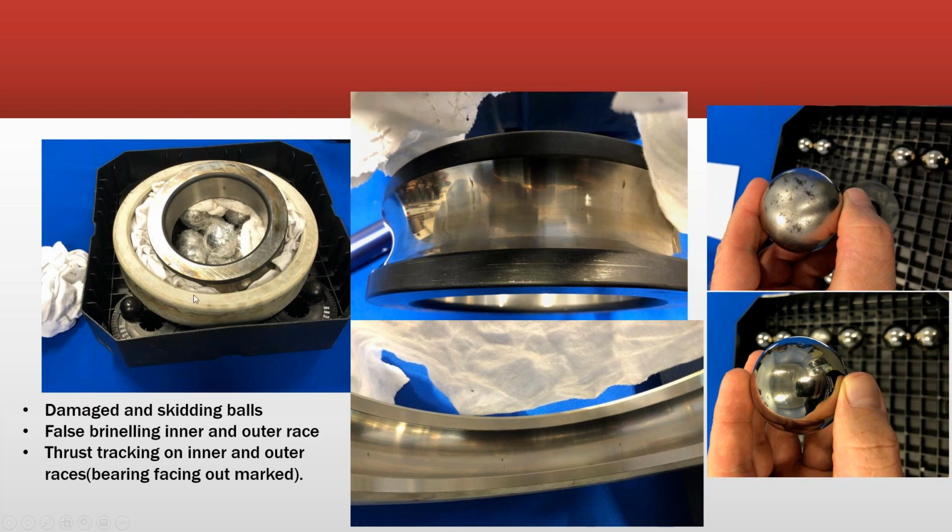So here's the bearing. This is what an M bearing is, an insulated coating on the outside. You know, probably the best one. Some people tried putting coatings on the inside. Don't even get me started on that. Shafts expand and contract, and ceramic doesn't.